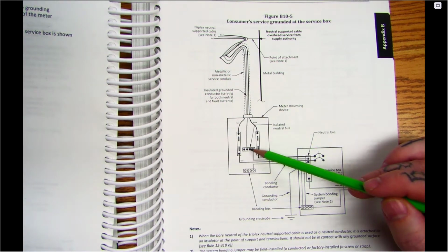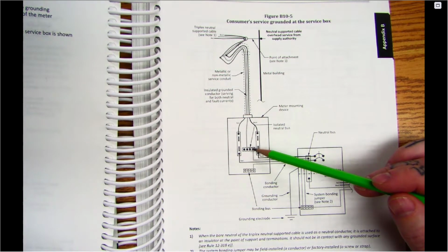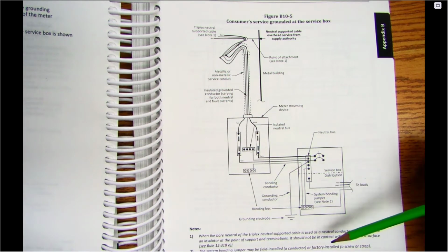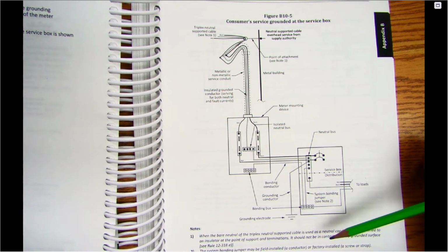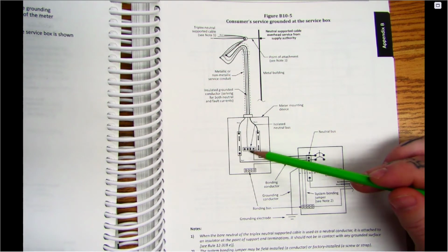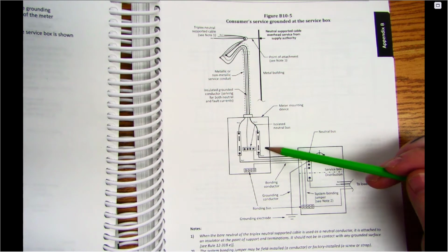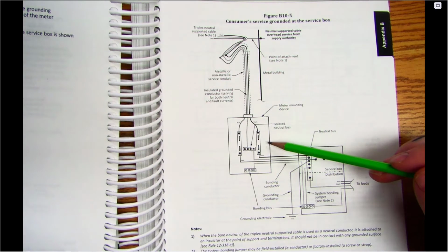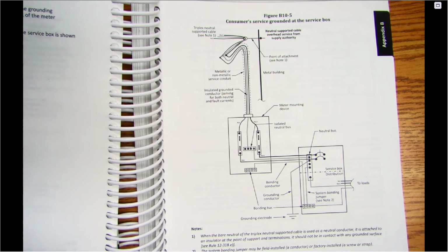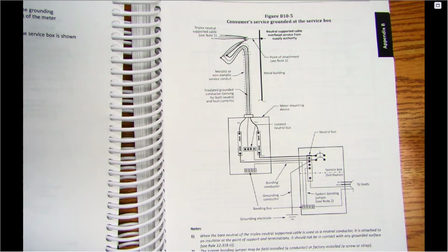You used to be able to just bond it here by not isolating this, and this is one of the rules that changed. So we would have to bring a separate bonding conductor back to that meter base so that that enclosure was actually bonded as well. If we didn't bring that bond through and this was isolated, now if this enclosure for some reason gets a hot wire touched to it, now this thing is live. Okay, if it's not bonded to ground, then we've got a potential issue, obviously an extremely dangerous issue. So we do have to carry that bond back now.